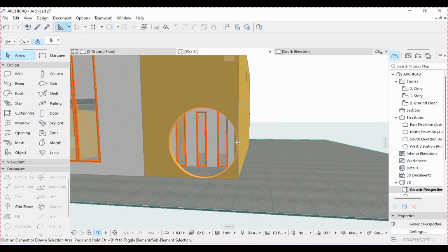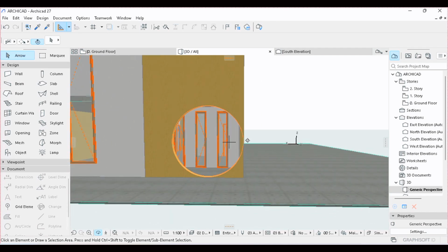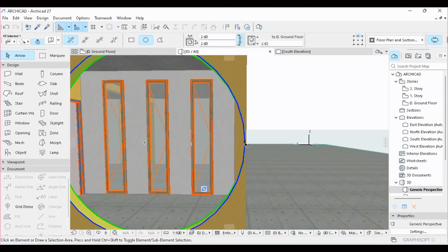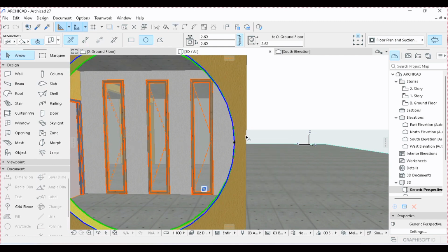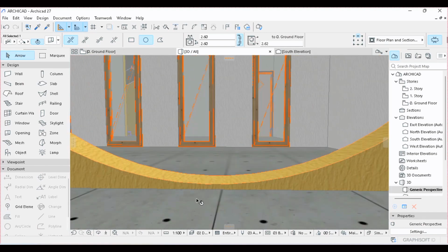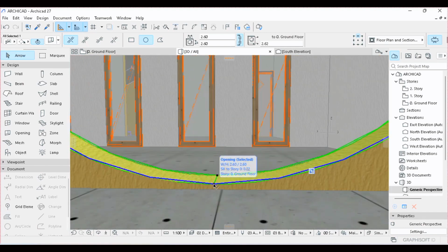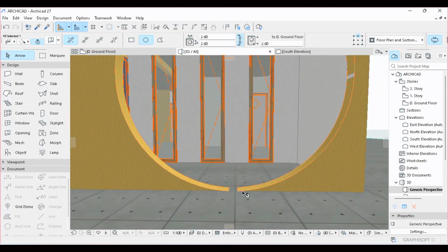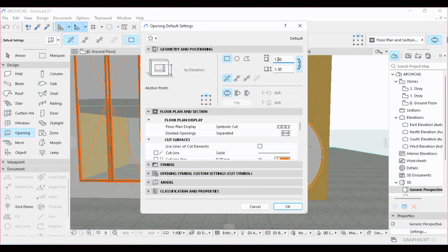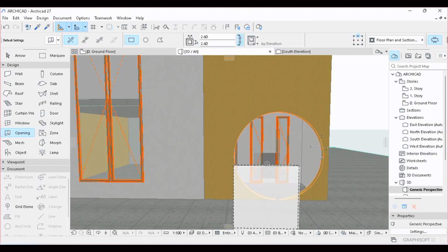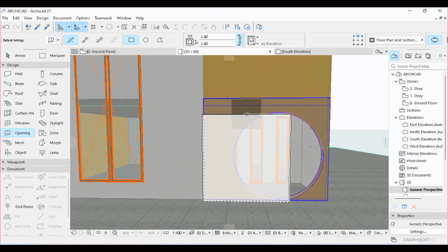I'll orbit by pressing O, and I'll now activate orbit. I'll try to look for a place to arrange the circle to be at the start of the wall. Then here I equally want it to start from the slab below. To move to openings, I'm going to use a rectangular opening of 2.60. I'm just going to click it here and I'll try to fit it in.